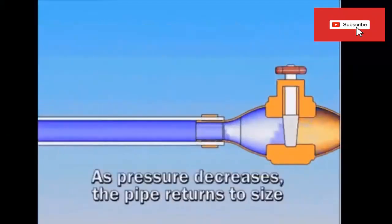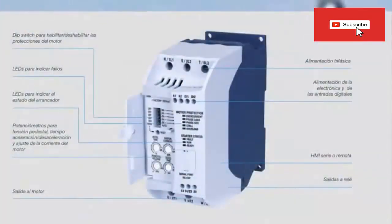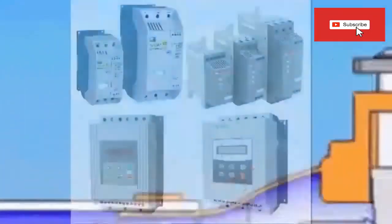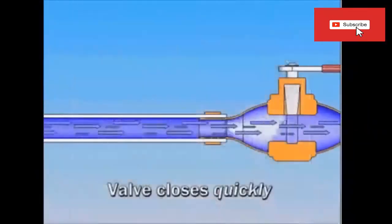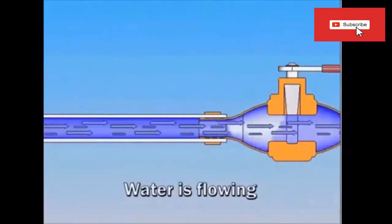To avoid water hammer, it is possible to use soft starters, which perform a progressive start and stop, through starting and braking ramps. Thanks to the use of soft starters with three-phase pumps, it is possible to avoid the effect of water hammer in our system, thus avoiding problems in the elements of the hydraulic circuit.